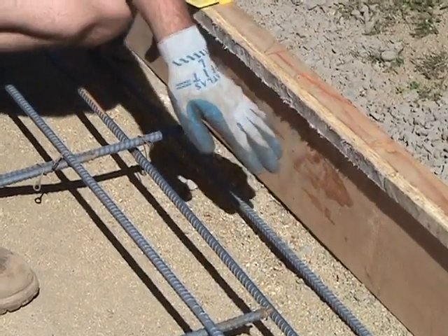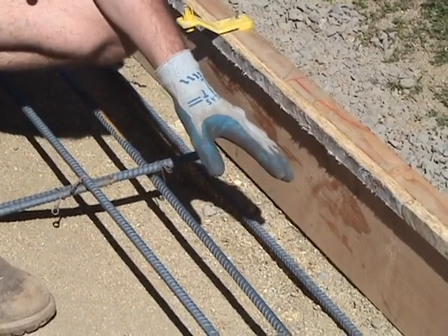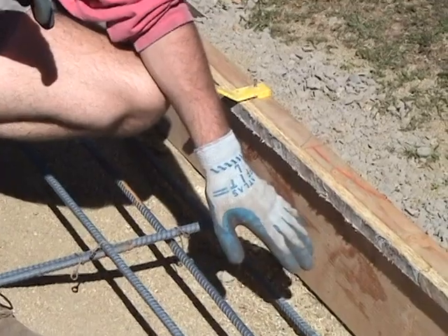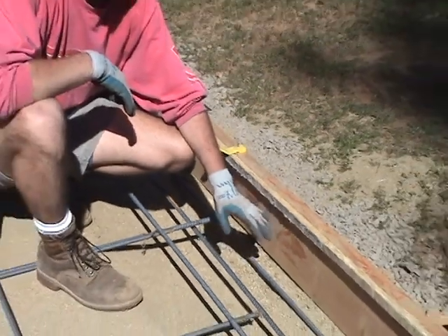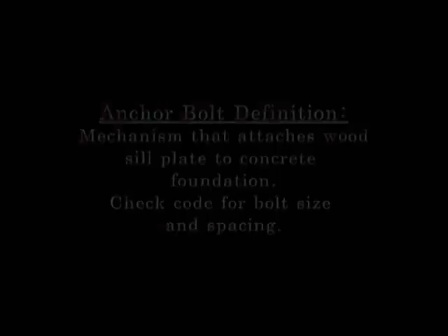Now, before you pour the concrete, and throughout the process, you want to make sure that there's no organic materials, no sticks, paper, any of that kind of stuff in the slab. Rocks, nails, anything like that is fine, but anything that's organic will decay over time and create voids in the concrete.